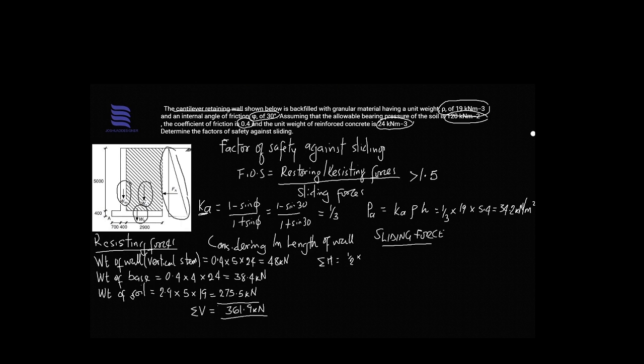Now the base of this triangle is what we have already obtained before as our Ka rho h, which is the pressure, the active pressure. Now I told you that's the active pressure. So let's just indicate it for clarity purpose that this part of the shape is the active pressure, right? The value there is equivalent to that of the active pressure.